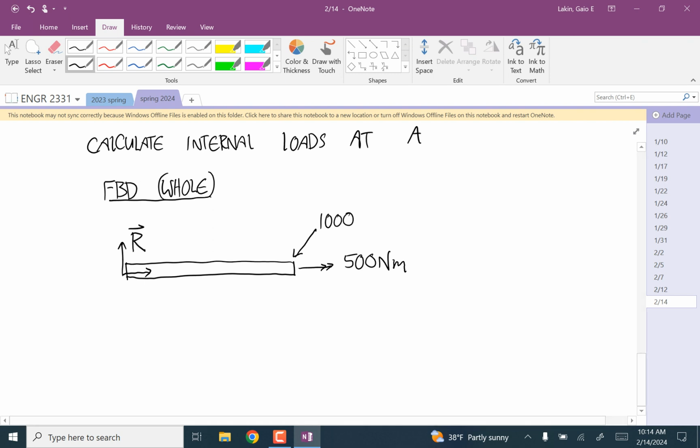And we also have a full vector of couples available from that fixed joint, but we're never going to be dealing with calculations where, like, you can imagine applying a force this way would require the wall to apply a couple about the y-axis. We're not going to ever deal with those. If you have something like that, just flip the problem in your mind so that it's in the plane that we're used to dealing with.